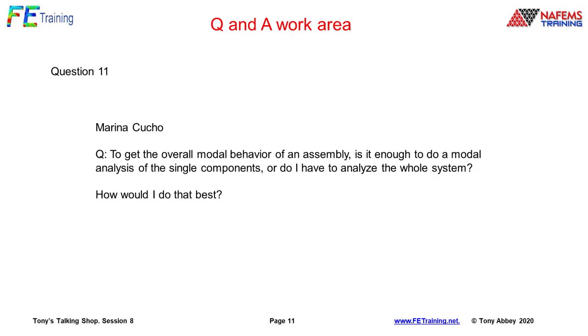resonant frequencies. Another approach, which is sometimes taken, for example, in suspension systems in the automotive industry, is to say, from experience, we want to make every component have resonant frequencies, let's say, above 300 hertz. And this can only come from experience. If I make sure each of my components has a resonant frequency above 300 hertz, when I bring them together, I've got some